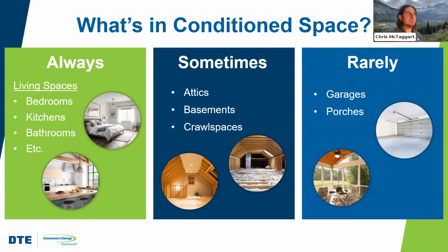The value there too is that oftentimes ducts and air handlers may be included in a crawl space. And then, if you have any duct leakage or heat loss off of those ducts, that's occurring in conditioned space instead of just being wasted into a vented crawl space.